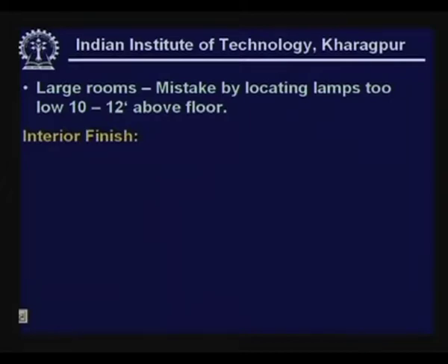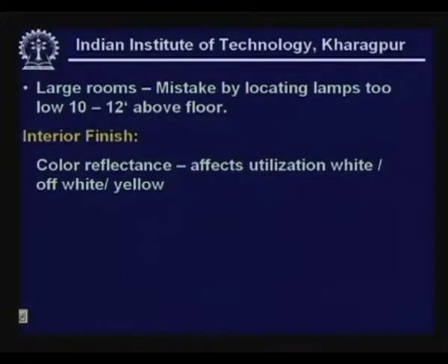In large rooms, never locate lamps too low. In fact, the common mistake is placing lamps too low. It is not required. Remember, if you try creating a large source of light, it is independent of the distance from the lamp. Now, coming to the finish, we said the interior finish does affect, and in fact color reflectance